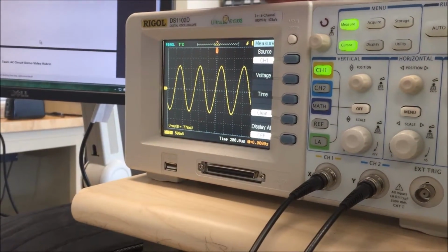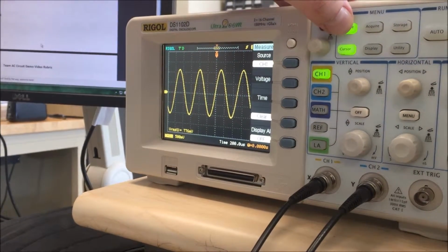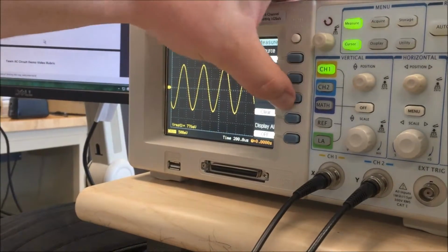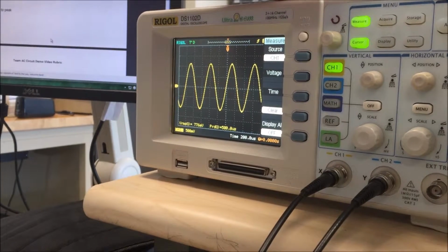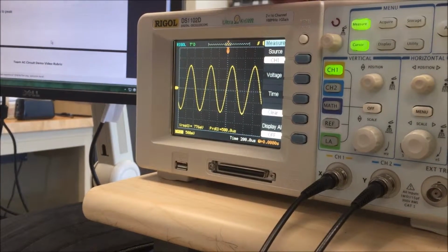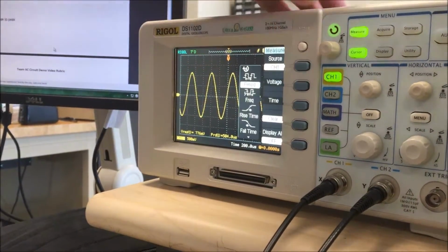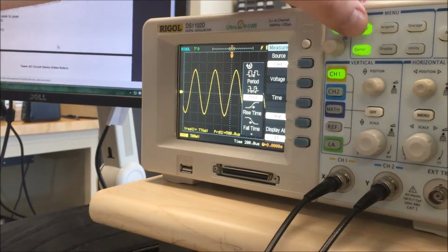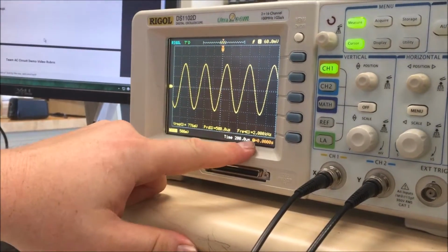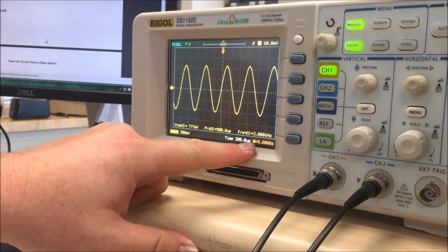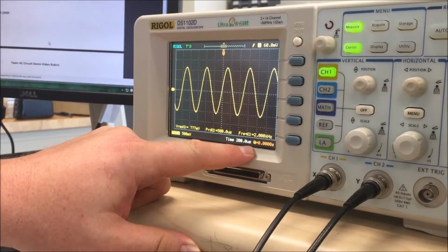which is 776 millivolts. Then we'll pull up the period point, which is in time. It's 504 microseconds. Then we'll go on to the frequency, which, when we turn off the menu, will be 2 kilohertz, my apologies. So that's how to do that all new school.